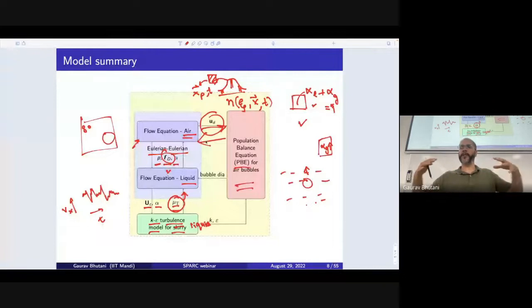As the bubbles rise up, they push the liquid, but the liquid cannot go out. So very interesting dynamics develop where you see circulation. The whole liquid starts to mix. When you say particle, you mean gas bubbles here. We will not talk about liquid particles because liquid is a continuous phase here. Whenever we use particles in the sense of polydisperse flows, they're always gas particles or discrete phase particles.